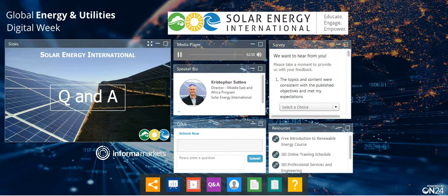Next question is, do you recommend microinverters instead of regular battery-based inverters? They're different. Most of the microinverters that are on the market now are all grid synchronizing types of inverters. Microinverters are really meant to be utility interactive and utility synchronizing, that export out into the grid.